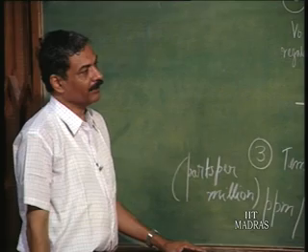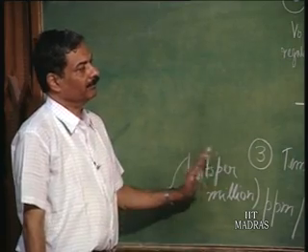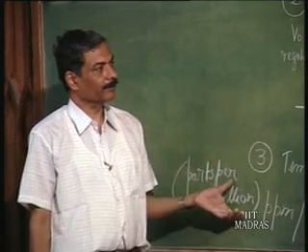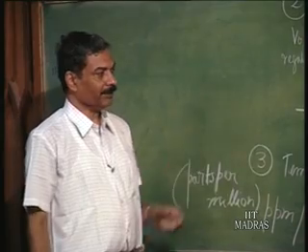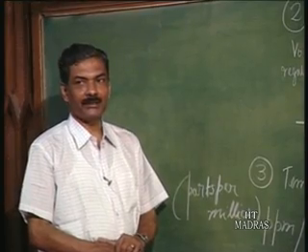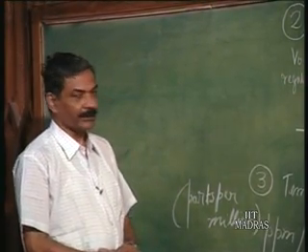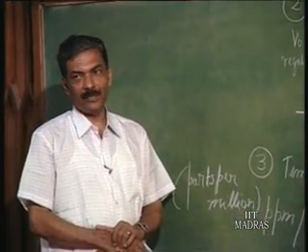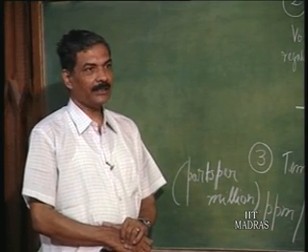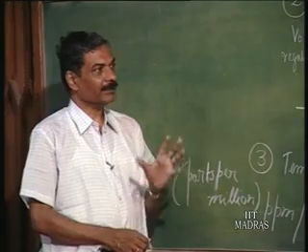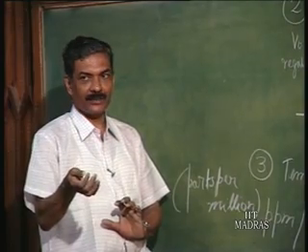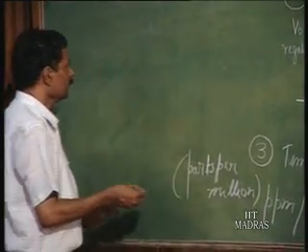This primarily depends upon the temperature coefficient of voltage reference basically. So, we tend to use voltage references which have 0 temperature coefficient here. So, these are 3 important primary factors which tell you how good your voltage regulator is. Apart from this, we have other parameters which are basically called small signal parameters, which are needed in trying to assess the quality of the voltage regulator in association with whatever is using that voltage regulator as a power supply. So, these parameters are